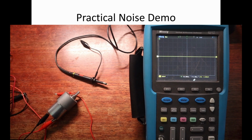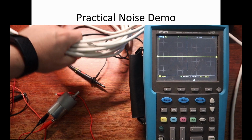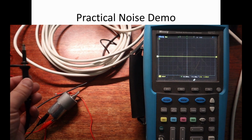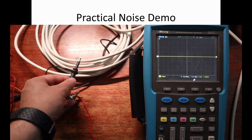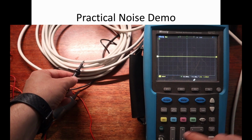Now, we're not going to connect this probe to anything, and we're going to show how we can induce noise into this probe. First off, I've got a cable here. And this cable is just a power extension cable plugged into our power point. But let's see what happens when we bring the probe of this right up close to our signal.